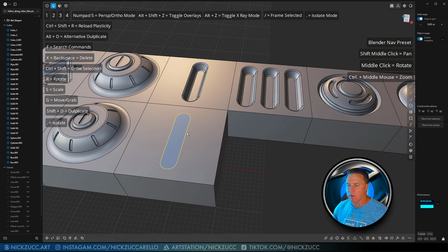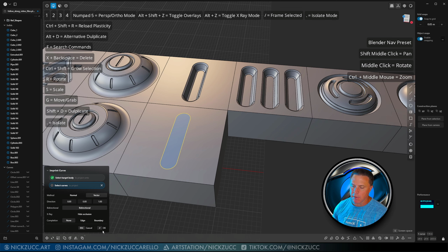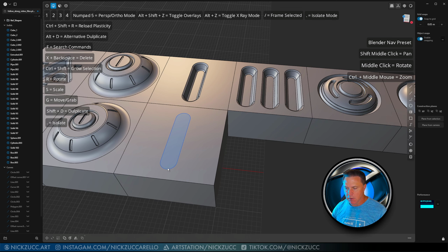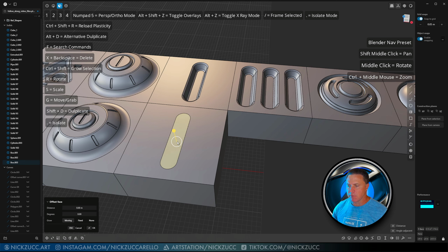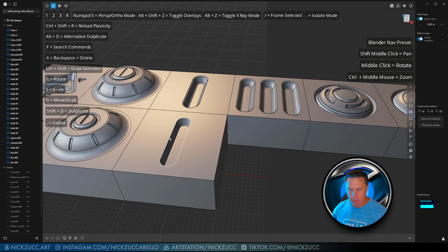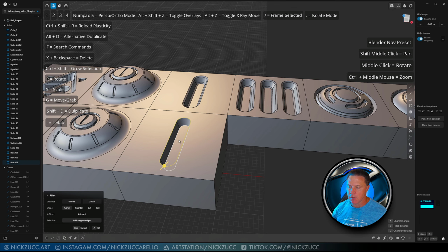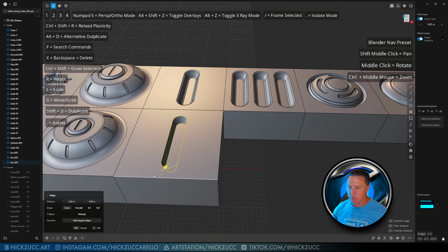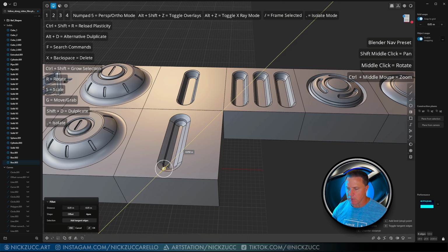Okay. We've already looked at how we can select this and tap Shift I, and that will imprint into this body. We can take the curve, select it with 2, hide it. So let's go ahead and tap 3 on this one, and I want to tap E to extrude it in because I want to do this tapering effect like this. Okay, tap 2, and I'm going to hold down Alt and Shift so I can select this ring and this ring together.